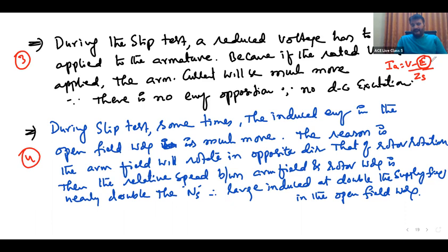But are you giving any DC current? No. You are not giving any DC current, then how much will it be? Very less. There will be some armature flux cutting, some voltage may be there, but that is very, very less. Actually, the generated EMF in our alternator is mainly due to main field flux. But that main field flux we are not giving. Therefore, no EMF opposition in V minus E. E is roughly 0, say. Then V by ZS, what will be the current? Very large. Current will be very large.